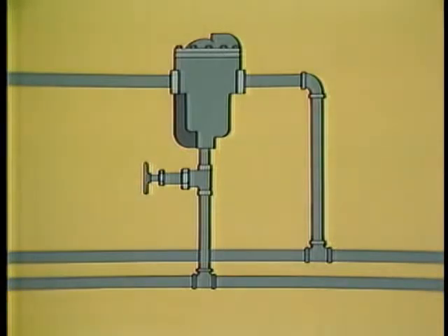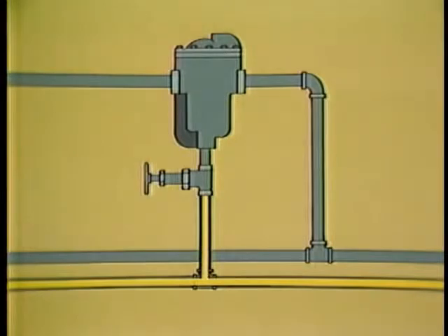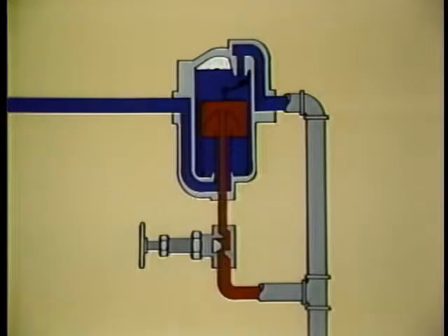For secondary steam recovery, the discharge of the metering valve is piped to a separator and then to the top of a secondary steam header and transported to other workstations. If the flash steam and non-condensables are to be removed but not used in a secondary steam system, pipe the discharge of the manual metering valve directly to the condensate return line.